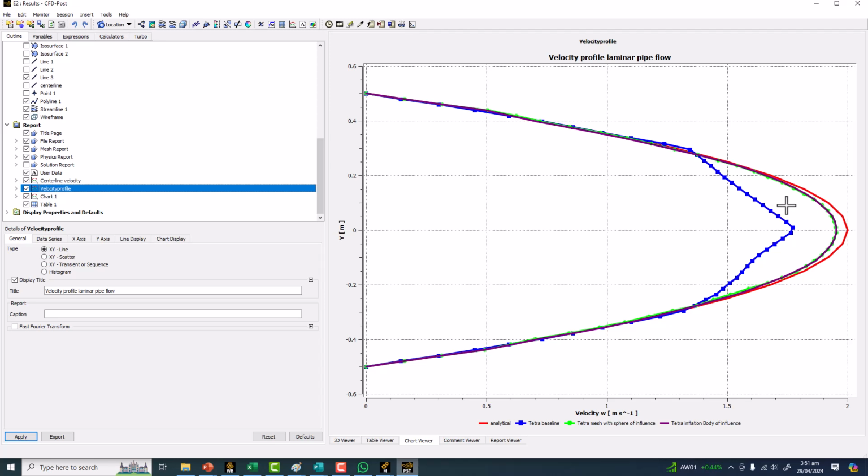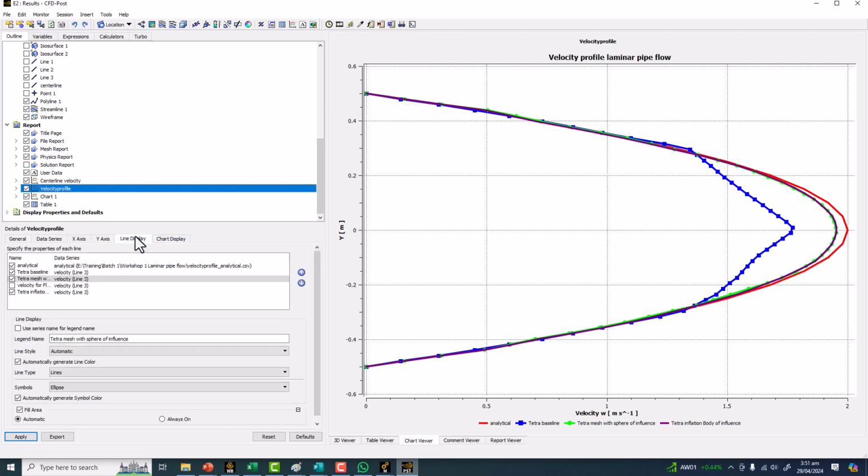So these are the results, and if I go to the plots, you can see the hexa meshing case. Here, in the pink color, is a multi-zone mesh, and the number of cells is only 25,000. On the other hand, the tetra meshing in blue contains around 160,000 cells, and the other two meshes have a lot of elements. So let's go through them one by one.